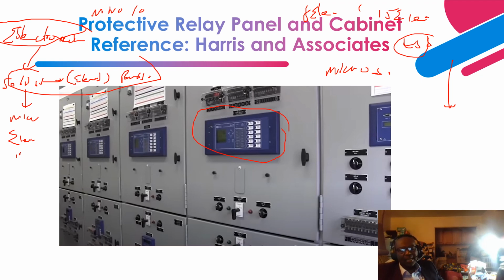So you can see how protective relays have evolved. The microprocessor relay does the work of all these discrete electromechanical relays, much more reliably, and offers a lot of enhanced features, such as monitoring of parameters, and the ability to download fault records and data from it in real time.